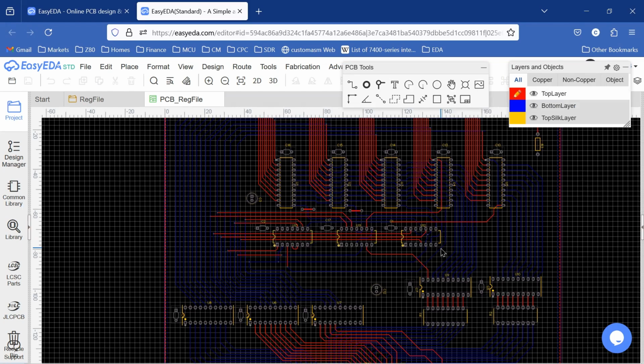These are NAND gates, I think, and this is just another AND gates, I believe, that are just doing combinational logic that we need to primarily drive the clock signals to each of the chips for their clock in signal and one output enable signal that's required here.